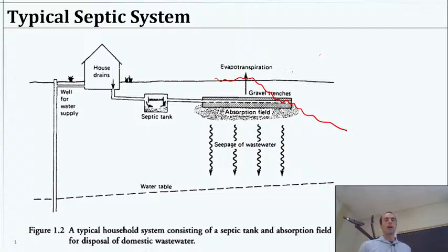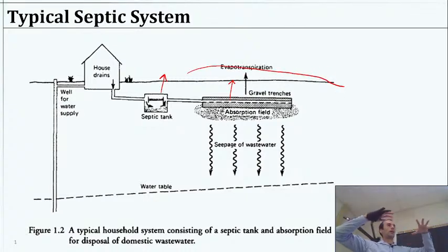There are a couple of exceptions, and this is something kind of interesting. Didn't put any slides here, but one thing you can do if you have soil that doesn't really drain too well, one option is to actually elevate everything a bit and then make a mound of dirt over your system and just pile it on top, cut down deep, maybe a foot or two, and layer that with gravel and sand.